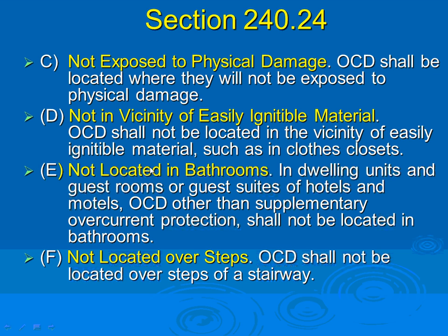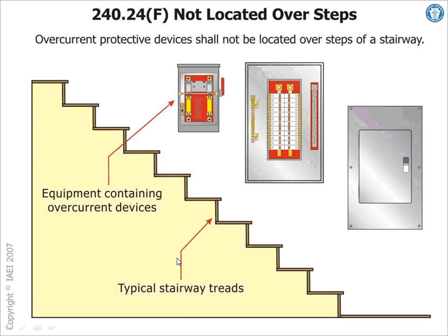You can't put overcurrent devices, fuses or circuit breakers in bathrooms of guest rooms or guest suites or hotels and motels and dwellings and so forth. Not located over steps. I'm sure somebody tripped and broke their neck, and they added this one in 2008, if you guys remember. You can't put them over steps now. You can put it over a landing, but not over the steps.